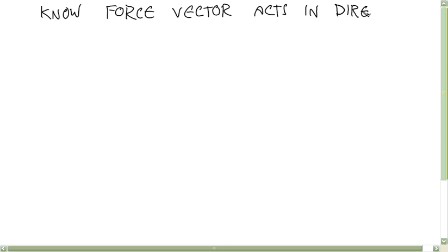Once I have that vector, I'm going to calculate the unit vector in that direction. And then I'm going to multiply that unit vector by the single unknown, the magnitude of the force, which is the cable tension. And that's going to give me a variable that only has a single unknown, say the tension T, and still represents a full vector.